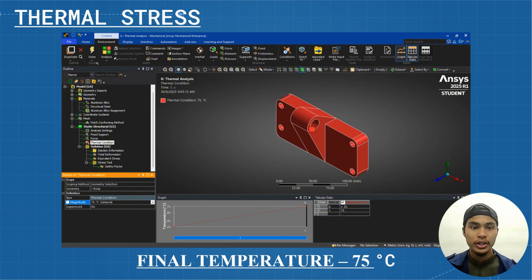First, component location. Not all parts of an aircraft engine are exposed to the higher temperatures. The bracket might be located in a cooler region where temperatures are moderated. Second, material limitations. If the bracket is made of aluminum, its operational limits are lower than superalloys. Aluminum alloys typically lose strength above 150 to 200 degrees Celsius, so the analysis might conservatively assume a lower temperature